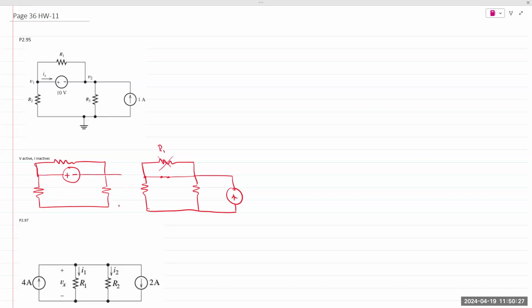And that is an important concept in electrical engineering. Okay? If you have a wire, anything in parallel with that wire is redundant or does not have any effect on the circuit. So again, when the circuit changes, let it sink in, look at the nodes, see what is connected between each and every node. Remember these concepts, and then you can apply your techniques.